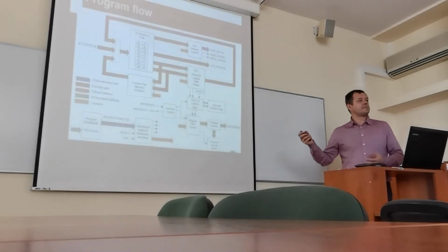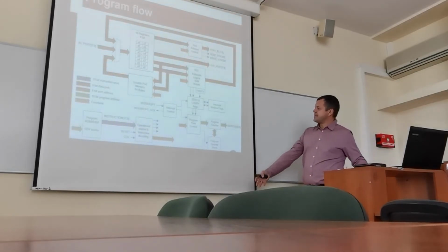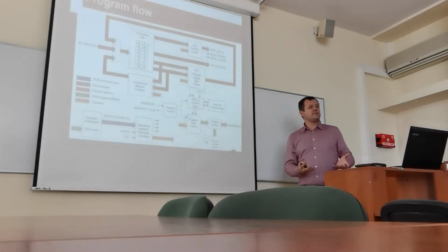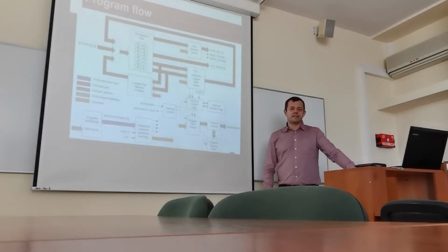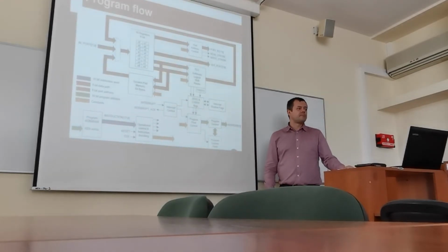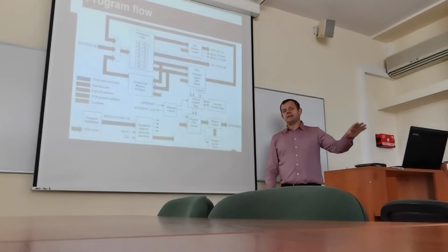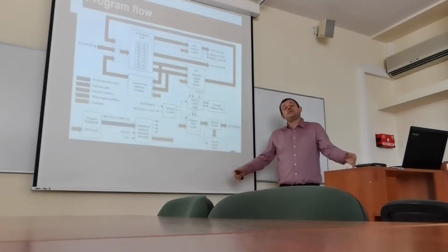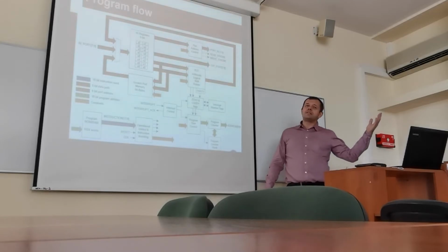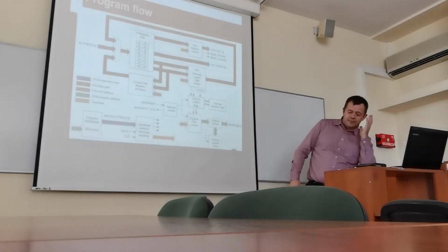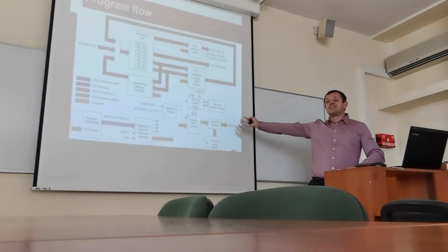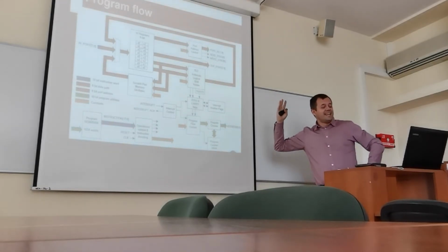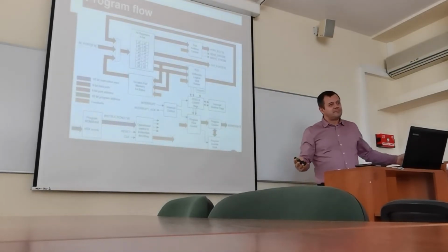And how it works in the case of a microprocessor: after reset, the program flow is very simple. After reset, the program counter is set to some value. It can be 0, it can be anything, because it really depends on the manufacturer, on the engineers. The engineers sit, have a cup of coffee or a beer, and say, okay, let's make a microcontroller starting at 100. Why not?